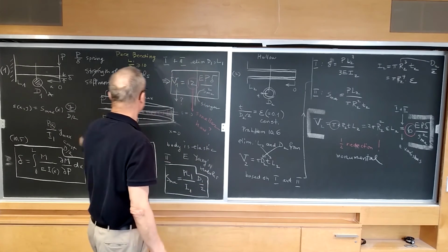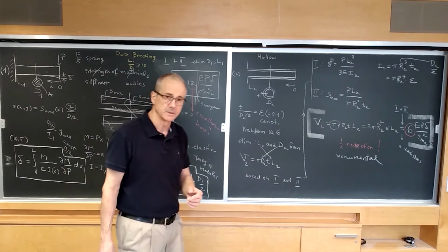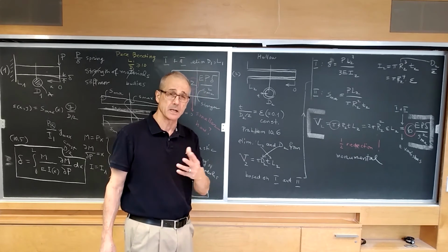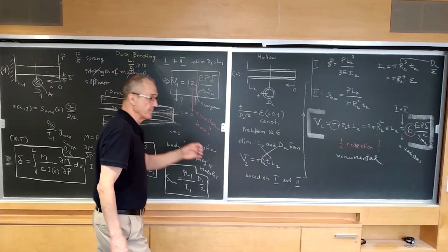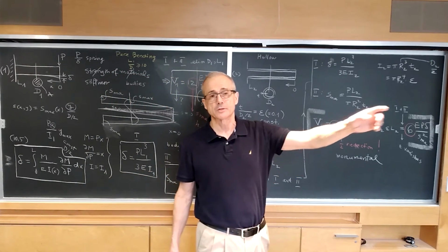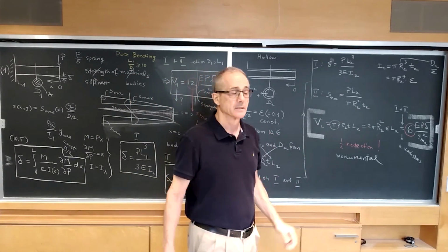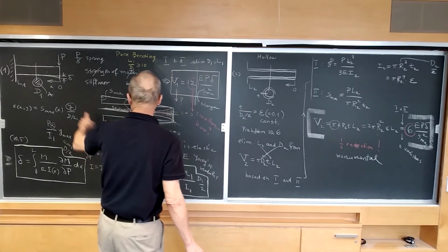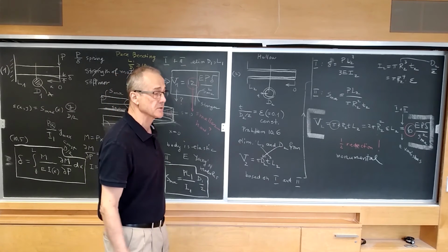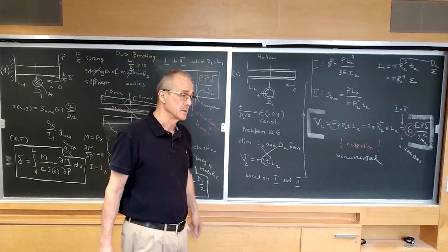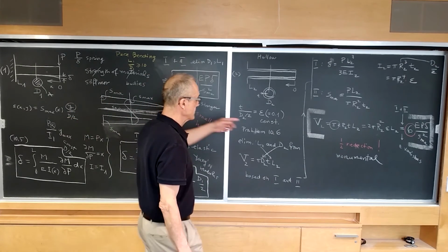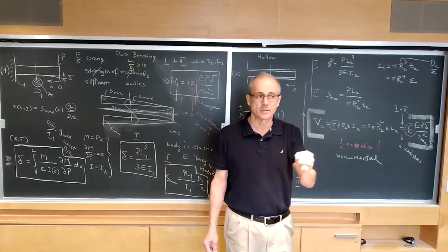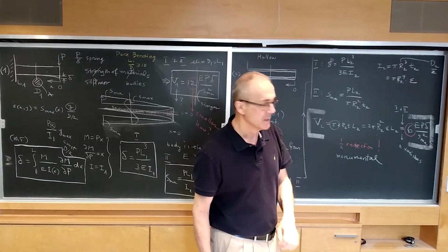It is a design that's asking to be improved. We'll see very soon, meaning in the next lecture, that nature itself improves this beam in the design of the branch of any tree you want. The branch is tapered at the free end, meaning it doesn't have an x-independent cross-section, even though the cross-section is solid. So freedom gives you these monumental surprises in the beginning of the evolution of the design.